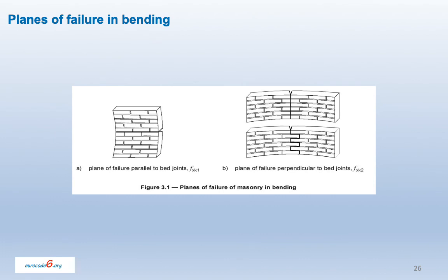For the flexural strength of masonry, Fxk1 is the characteristic flexural strength parallel to the bed joints, and Fxk2 is the characteristic flexural strength perpendicular to the bed joints. The values for use in the UK are shown in the National Annex. Annex E of the Eurocode provides the bending moment coefficients required for flexural design, and Annex F of the Eurocode the limiting dimensions.